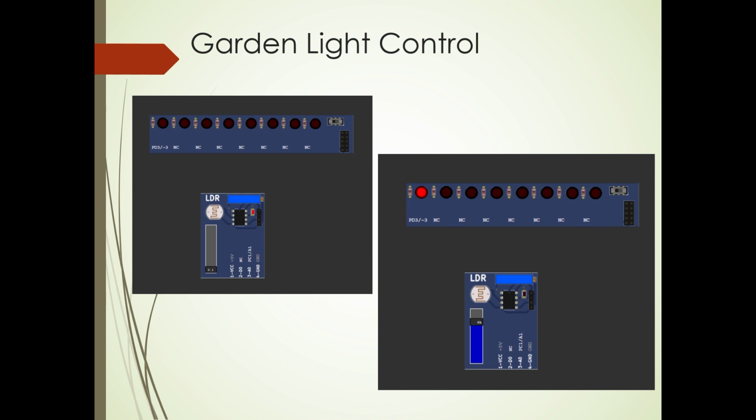So an LDR is also referred to as a photoresistor, photocell or photoconductor. LDR resistance values range from many megaohms in complete darkness to only a few hundred ohms in strong light. As a result, these resistors are widely used in a variety of applications due to this variation in resistance. The wavelength of the incident light affects the LDR sensitivity as well.